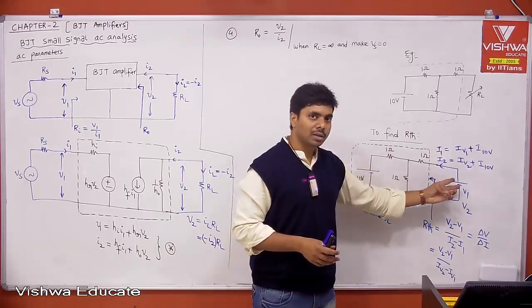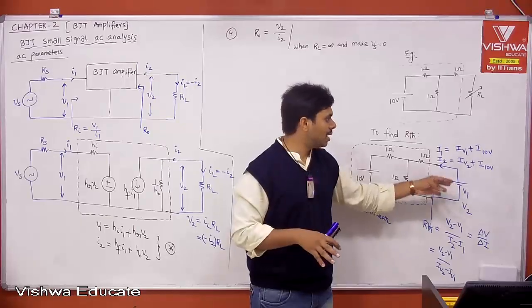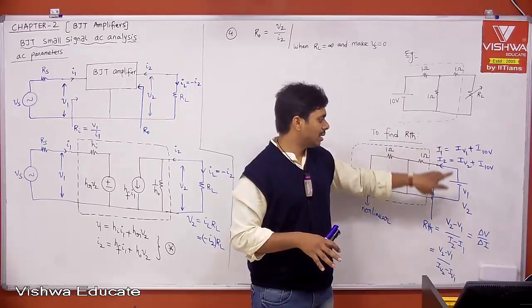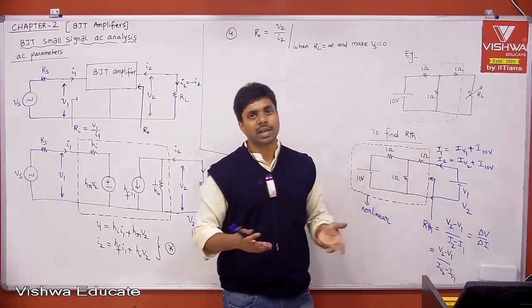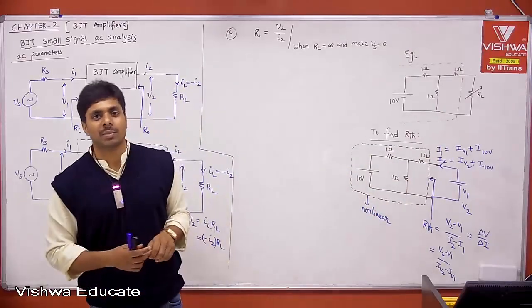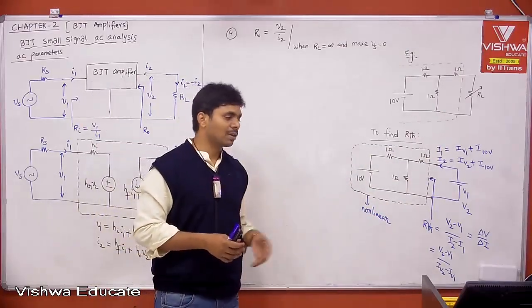Then V2 minus V1, which is 20 minus 10, is 10 volts. Then calculate I2 minus I1, and the ratio of delta V2 minus V1 by I2 minus I1, you will see 1.5 ohm. That is your Thevenin resistance, which used the methodology of shorting the 10 volts battery.